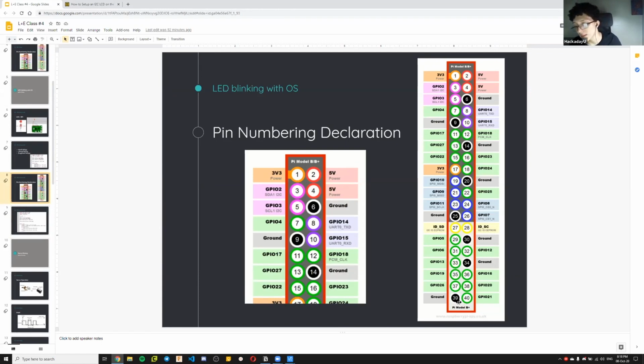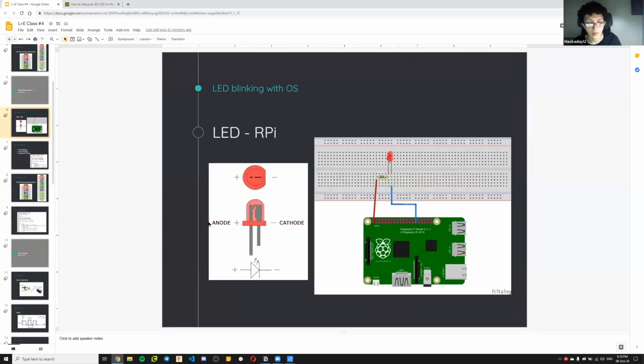I used these two, so I connected the negative, or the cathode, of the LED. The resistor could have been on the positive or negative side in this case, okay? So you could just put it here and connect the positive right on the LED, with the resistor between this pin and this one.